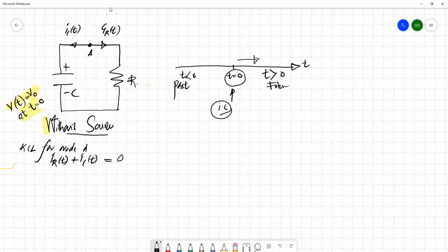Okay. So these currents are marked based on the passive sign convention. Passive sign convention means that if you mark the current, then we can mark or define the induced voltage across the element. The current is flowing into the positive terminal of the element or node. So this is positive, this is negative, this is positive, this is negative. Current flowing into the node is marked as a positive terminal. Based on the passive sign convention, we mark the induced voltages and currents.